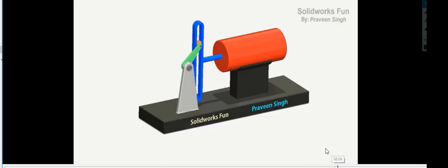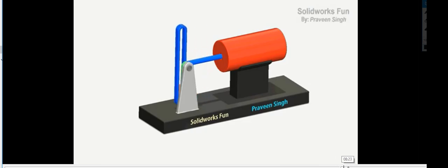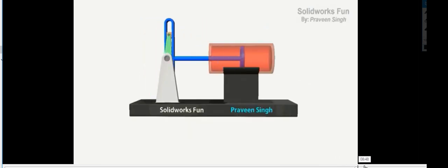Then we saw what a double slider chain mechanism is. You should not go into detail. First one is the elliptical trammel, which draws an ellipse with its edge. Then the Scotch yoke mechanism. Last one is Oldham's coupling.